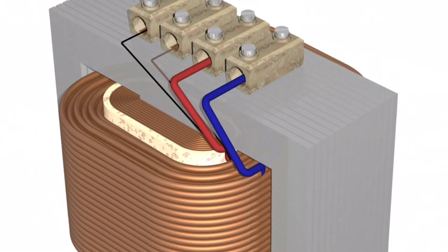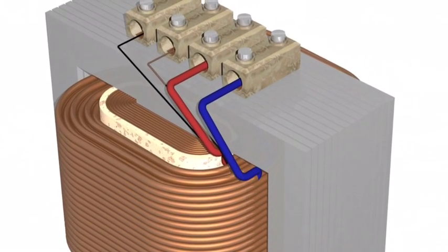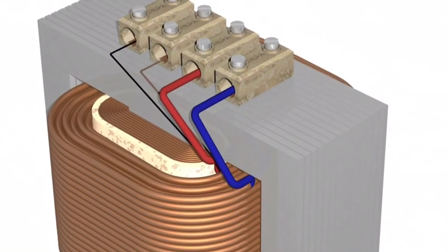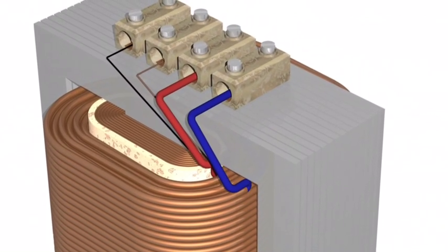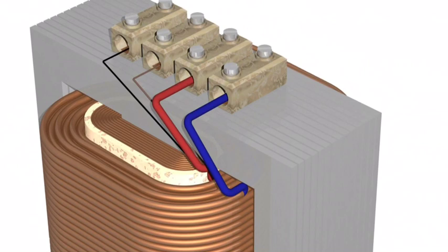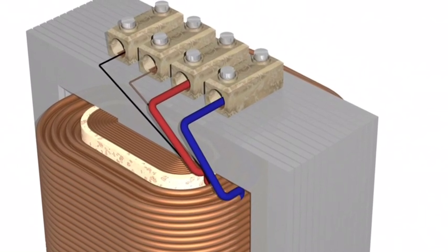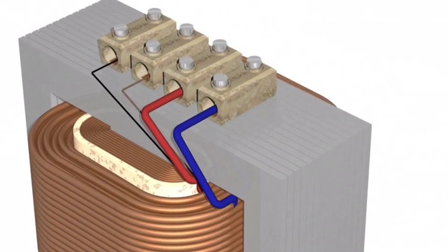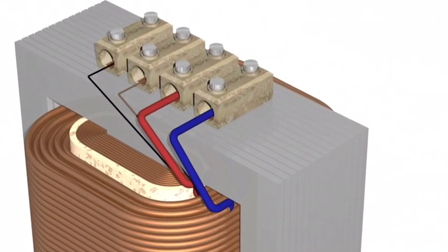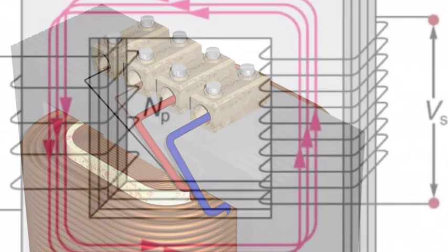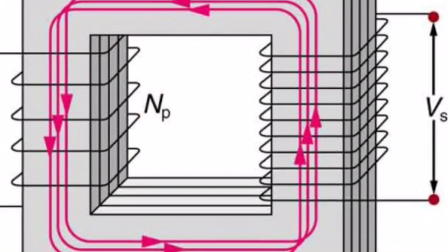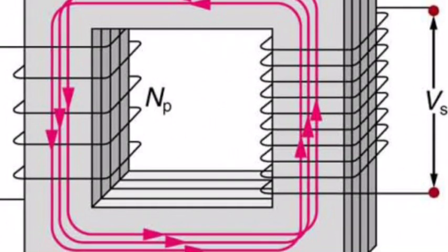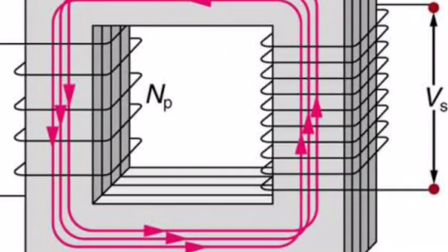Transformers. Transformers are an invention made to change the voltage in AC. This works by having a first wire in the form of a coil have alternating current pass through it. As the current changes, the magnetic field also changes correspondingly. Then the magnetic field can be linked to a second coil by having a ferromagnetic core pass through the two coils. Finally, the fluctuating magnetic field will induce EMF into the second coil, due to Faraday's law.